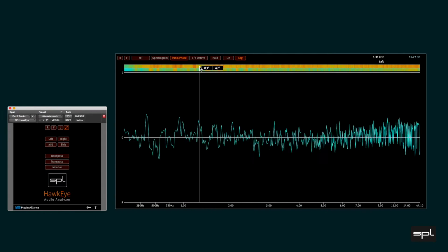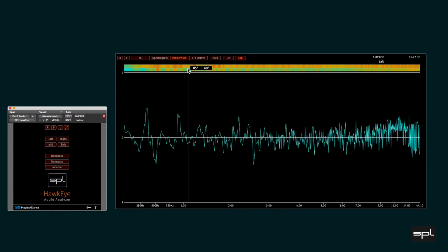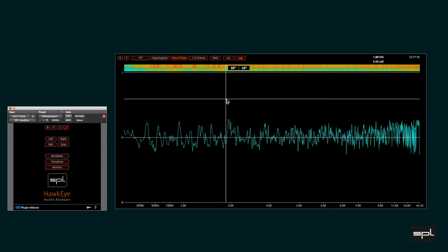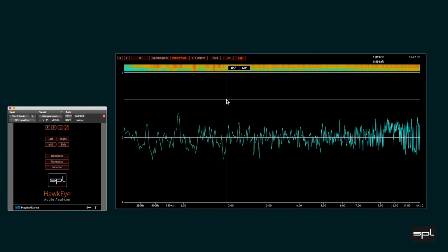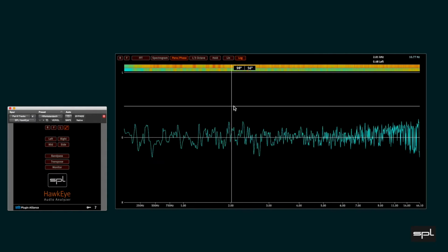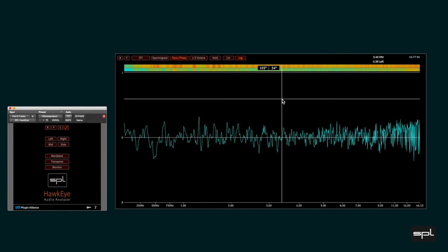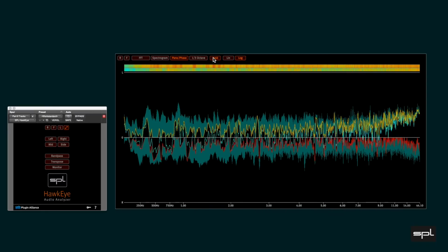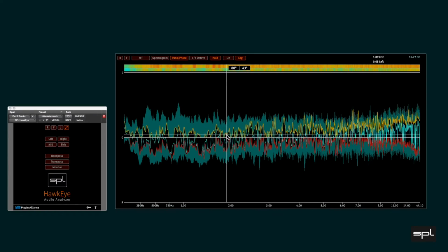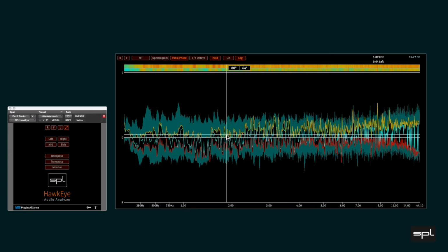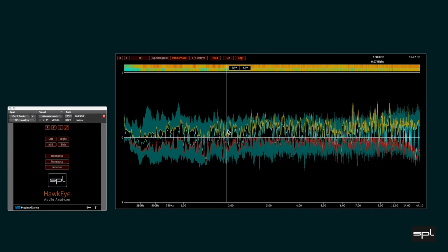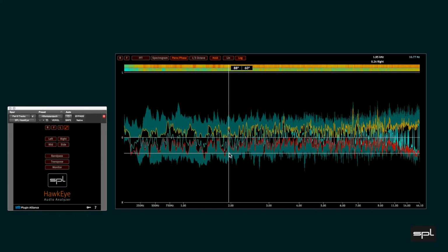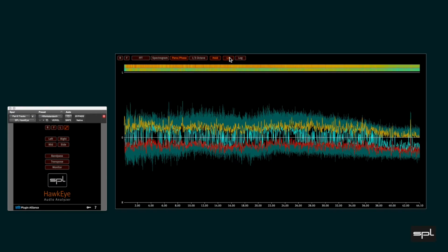Solid red marked frequency ranges below 4 kHz should get a deeper investigation, because they are an indication that energy may be lost due to frequency cancellation. Especially in the bass area, this can be crucial. Hold activates two momentary peak hold lines, red and yellow. They indicate the falling peak values. The petrol colored area holds the maximum peak values. And again, there are the linear and logarithmic buttons as discussed previously.